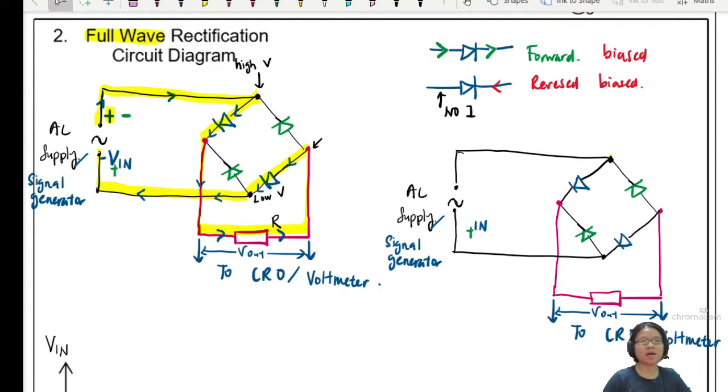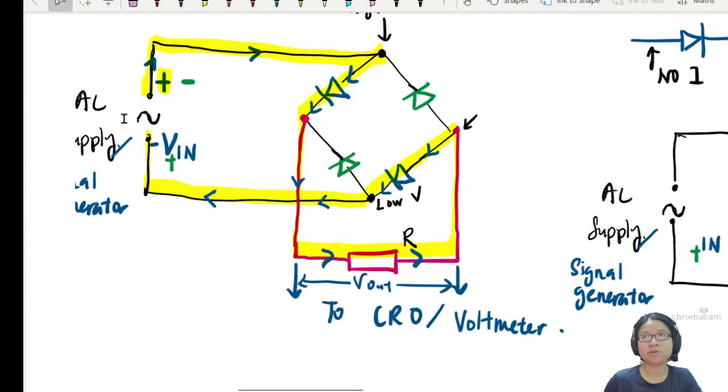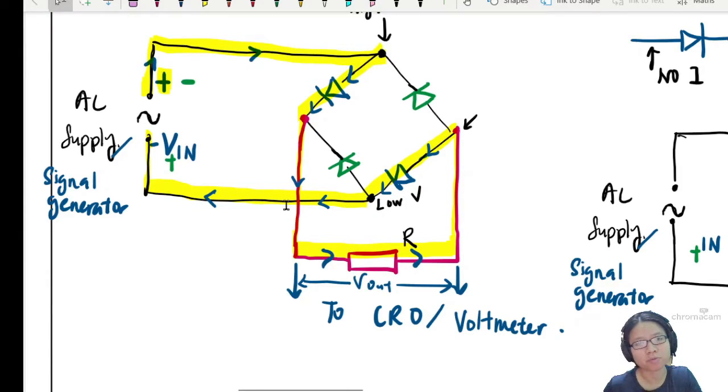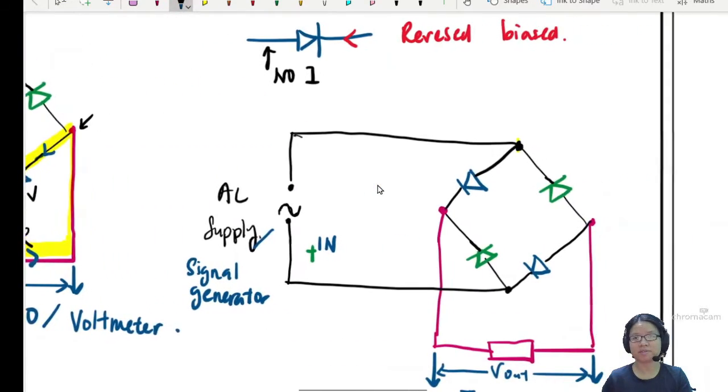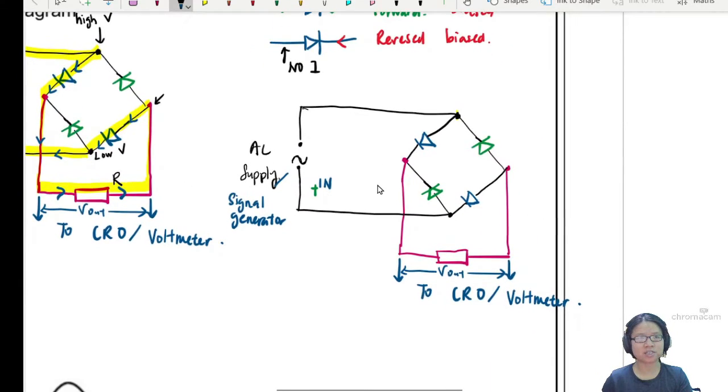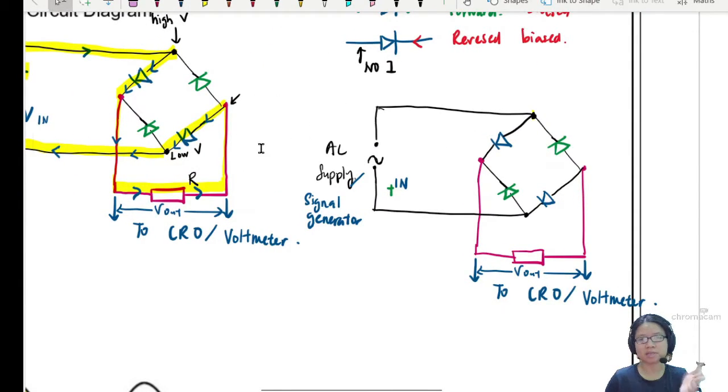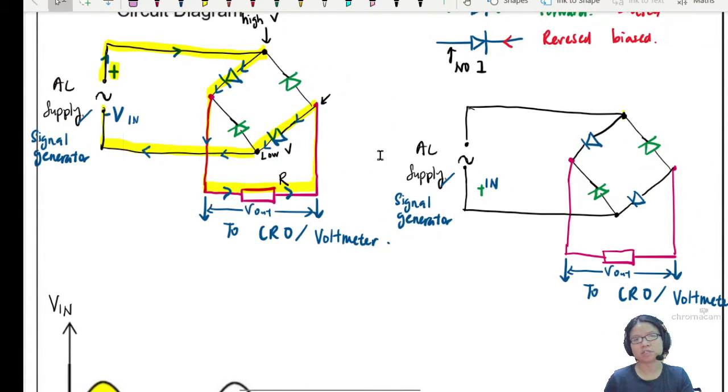All right, I'm back, and now we are ready for the second half cycle. So the first cycle, I have left it here, right? The current will flow in the direction of the blue arrow, so it will trace this way. So now we're going to swap the terminal such that this bottom one is positive and this top one is negative, okay? So I'm going to just gently, slowly nudge this away. All right. And we are ready for the next one here. Brand new and fresh. And just in case you want to double check, it's the same circuit. Okay, I didn't change anything. The diodes are still pointing downwards for the blue one. The green one is pointing upwards.